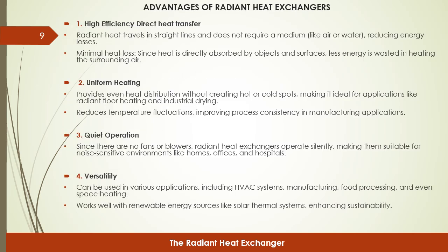So below are some advantages of the radiant heat exchangers. They have high efficiency direct heat transfer, since it doesn't involve too many mediums or any transport fluid. There is uniform heating, which provides even heat distribution without creating hot or cold spots, and it reduces temperature fluctuations, improving consistency in the process. So there is uniform heating.